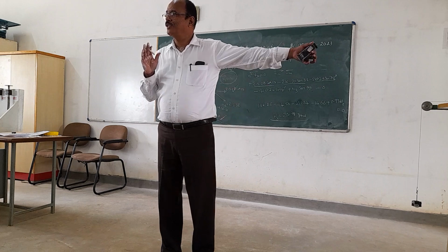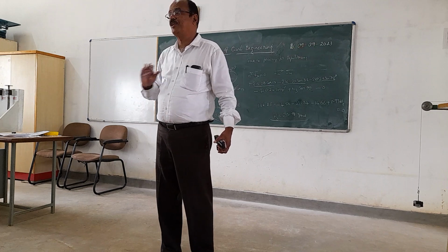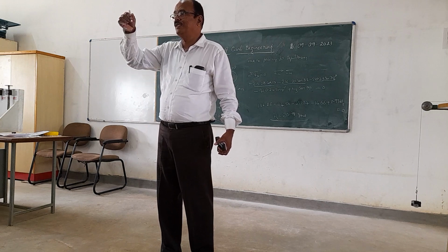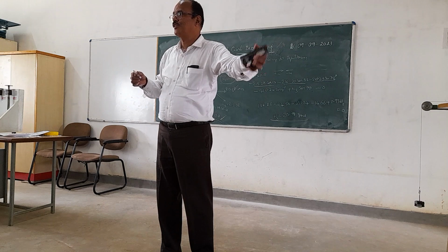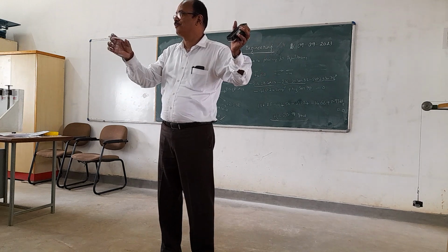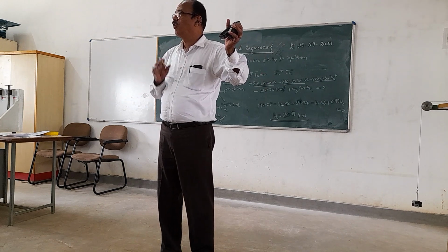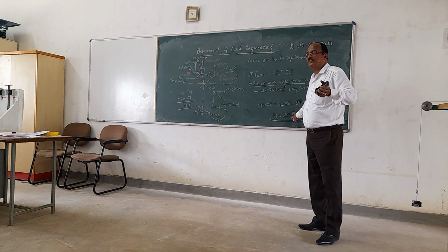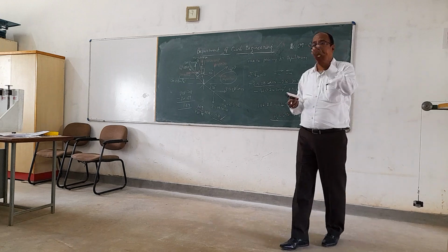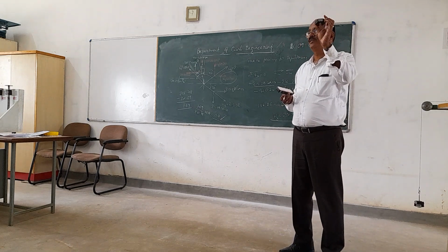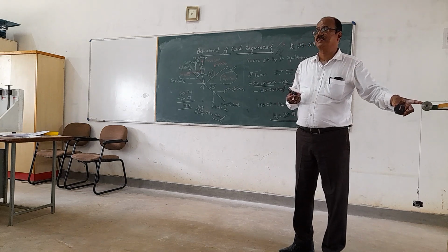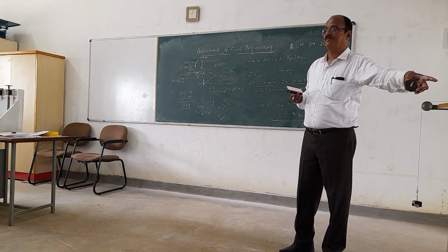With four forces applied, the system was not in equilibrium at the center ring until you applied a force of some magnitude, and then the point shifted and was brought to equilibrium. Theoretically you have to apply 201.78, and experimentally you applied 200.09. The percentage error is about 0.8%, mainly due to the friction within the pulley.